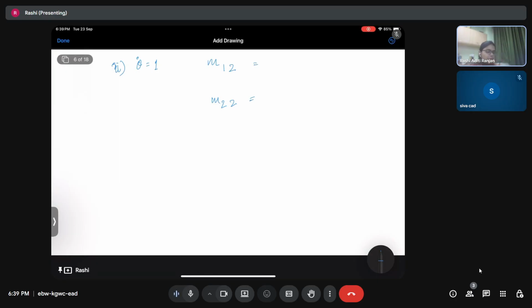We don't have any kind of linear velocity or translation velocity input that is being given. Rather, it's an angular velocity. But the point 1, which is our trailer, is translating. So we need to convert our angular velocity into translational velocity and then multiply it with mass.